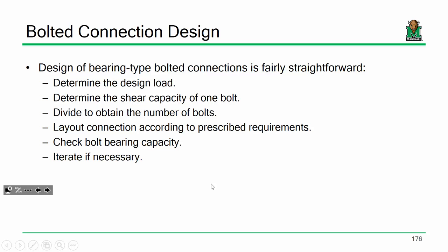Now, that's not enough. I mean, just saying, oh, you need 10 bolts, that's not enough. You have to actually lay out the connection according to prescribed requirements. So make sure that you've got bolt spacing met and you've got edge distance requirements met and what have you.